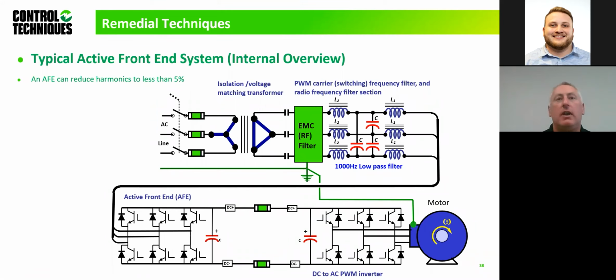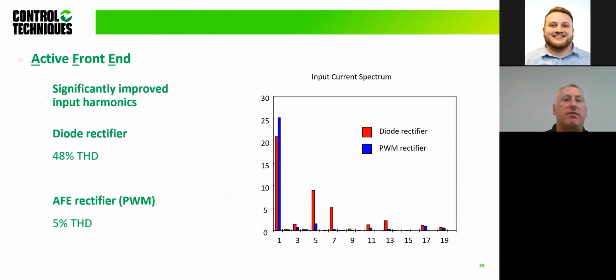Okay. So moving on, active front ends and their typical performance. Again, just so you can compare it to the diode rectifier, yeah, you pay more for it. It's comparable to an 18 pulse solution as cost, but with the performance of reducing that THD, now you can start thinking, oh, I don't have to put my generator to 3 MVA, can I bring it down? Okay.